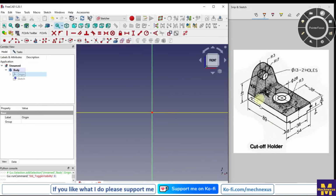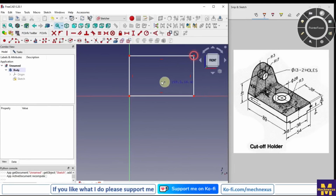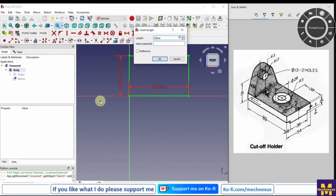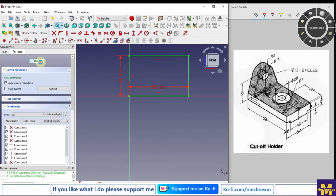Now we will read the dimensions. This is 89, and this is 41, and this outer radius is R17. So I will select a rectangle and draw it, and then give dimension 89 and vertical height 41 plus 17, so 58, and then I will close it.